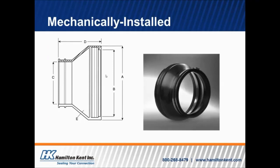So here is a typical mechanically installed boot connector. You can see the dimensions here. The A dimension on the far right is going to be the most important for the hole size in the manhole. And then the C size is the other most important dimension, because that's where the pipe is going to be coming into the boot connector.